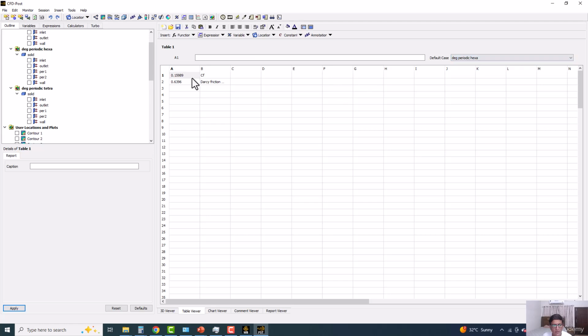It's almost the same with scientific digits to second order accuracy. So they are exactly the same data. Only in the case of tetra meshing is it a slightly higher value, but they are almost giving us the same results. So it means that the 30 degree sector, even with tetra meshing, although hexa meshing has a finer mesh, gives us the same results.